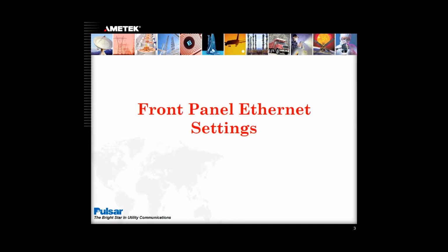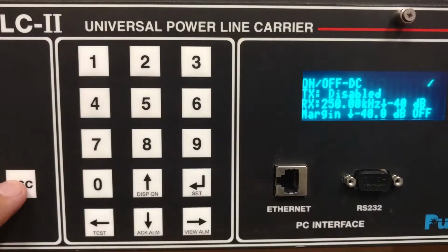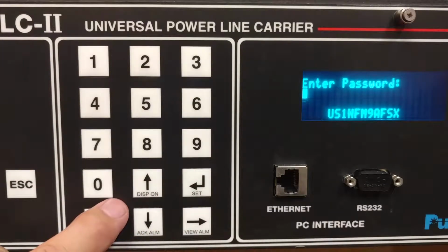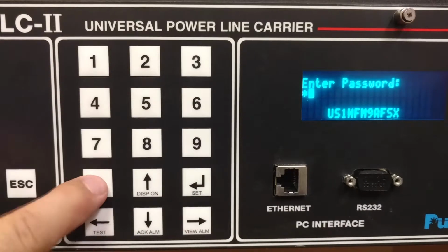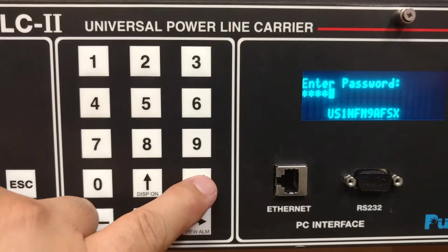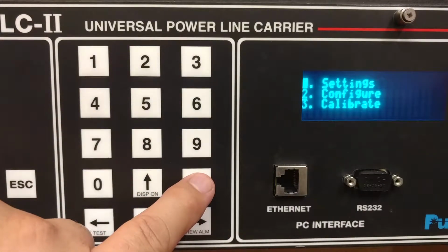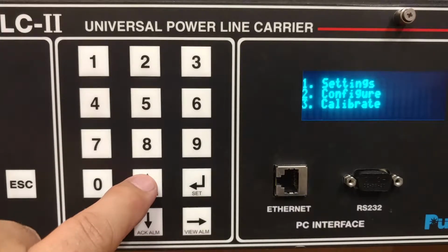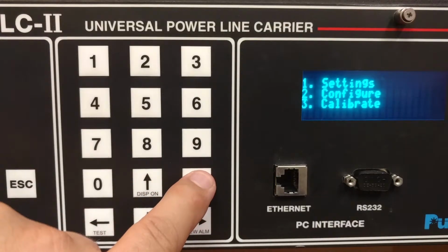UPLC Ethernet settings are accessed only from the front panel. With the unit powered up, press the Set button. If it is a new factory default unit, the front panel password is 4050. Enter 4050 and press Set again. The front panel display will now show 1. Settings, 2. Configure, 3. Calibrate. Press 2 or use the cursor keys to highlight 2 and press Set.